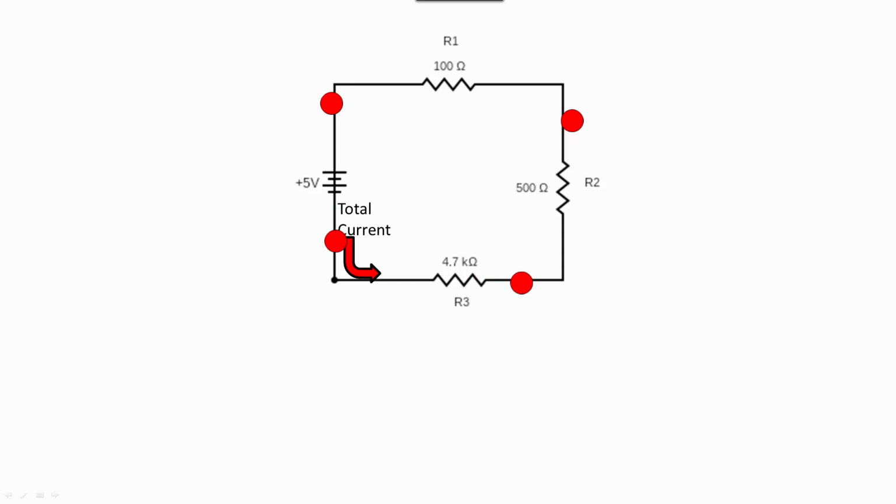Here is an example of a circuit and our first look at a schematic. The component on the left is the symbol for a battery and obviously the voltage source. The short line at the bottom represents the negative terminal of the battery, and the longer one at the top is the positive. R1, R2, and R3 are the symbols for resistors, which are electronic components manufactured to have a certain resistance in ohms. Here, the resistors represent the load.